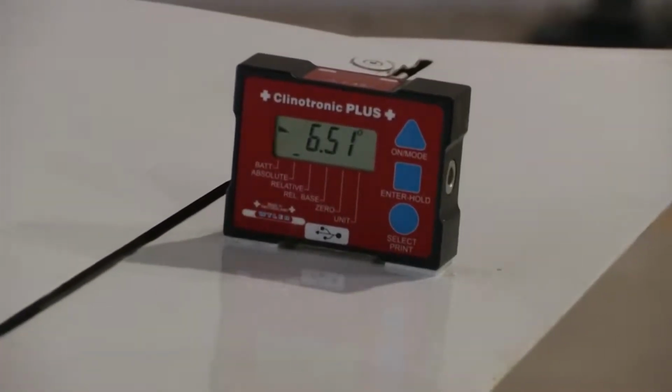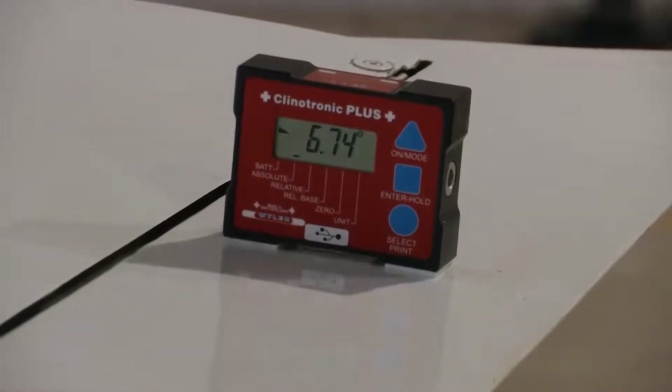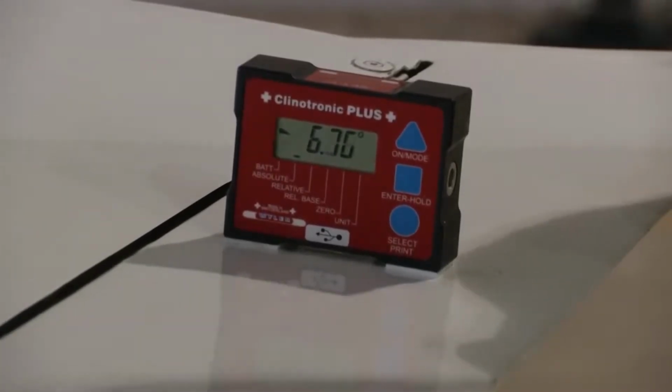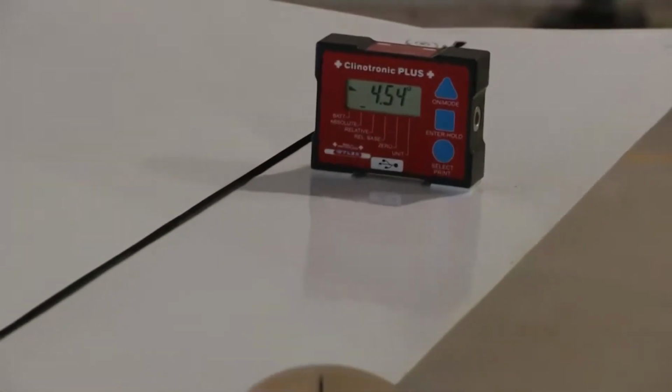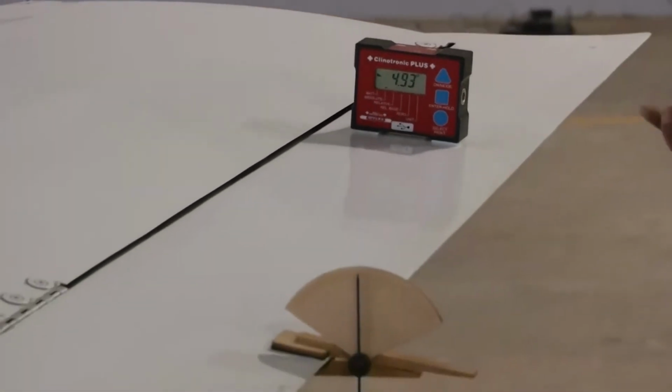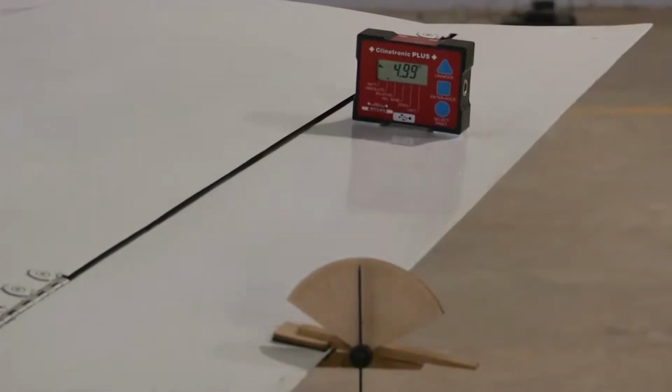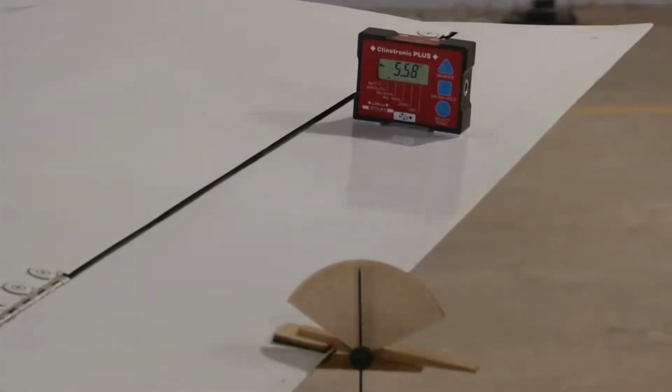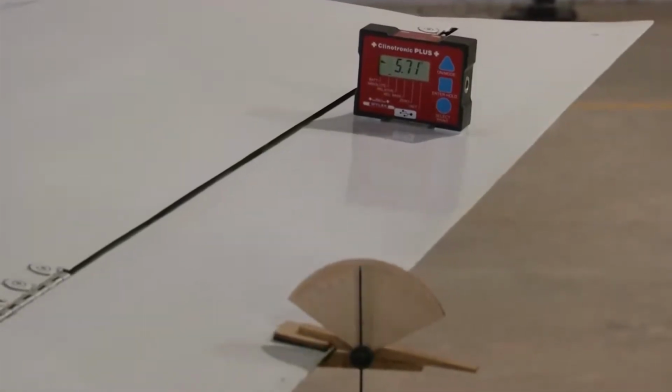So while varying your control stick, you can determine what voltage you are getting in your LabVIEW with a particular deflection, using our LabVIEW software. Now after setting my reference point, the next step was to load your LabVIEW program and deflect your control surface in both directions, downwards and upwards with respect to your reference point.